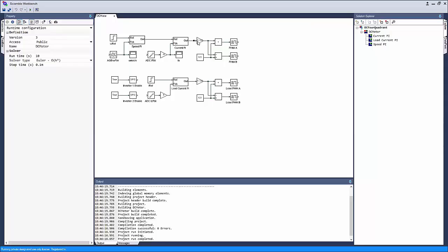And we generate this reference output voltage using a full bridge converter. The duty cycle for this full bridge converter is generated using the formulas that we had shown in the slides before. To emulate the load torque, we have a DC generator that's coupled, and that is run in torque control mode, or effectively current control mode, because torque and current are proportional in a DC motor. And both of these inverters are enabled.